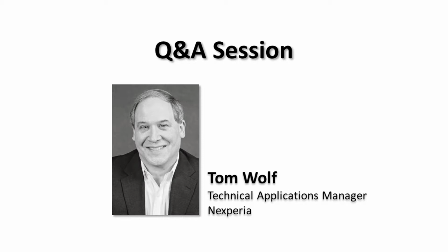Again, what you're doing is you're living in the linear mode operation of the device. You're taking a long time to turn it on, with high currents for long periods of time, and the simulation will absolutely compensate for that. So you're right, you can indeed use our MOSFETs. Particularly the big ones, the LFPAK88, the 8x8 millimeter packages, are built for those very high current applications that stay in the linear range for a long period of time. So yes, the LTSpice model will compensate for that.